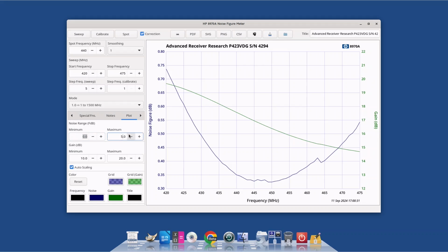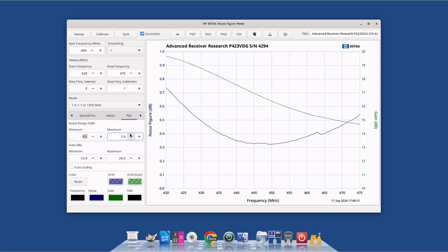To create a memory trace, first load a previously saved plot or capture a new one. Press the memory button, which is the button with a camera icon, to transfer the measurement trace to the memory trace. The memory trace is shown with a dotted line, but will be obscured by the measurement trace if they are identical. The memory trace may be hidden by disabling the checkbox on the Notebook Options page. The memory trace is deleted by using the right mouse button to click the memory button.